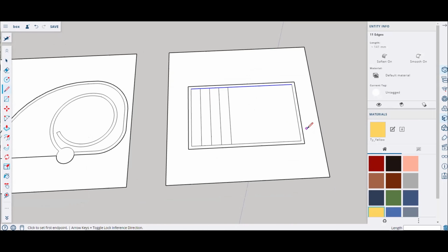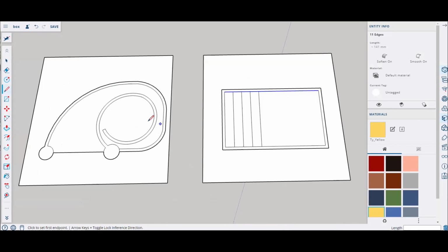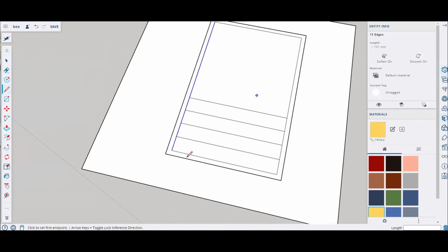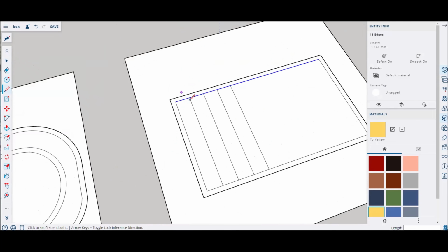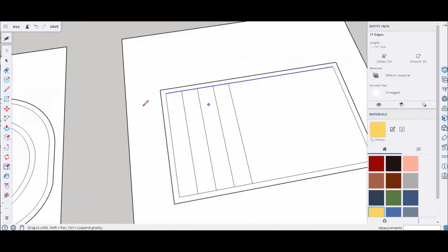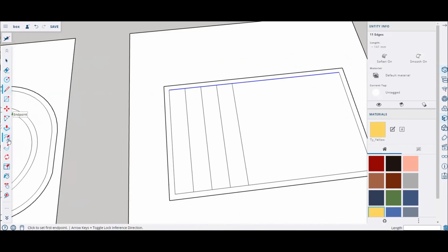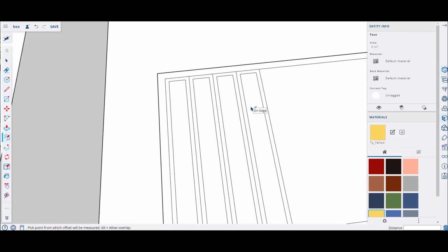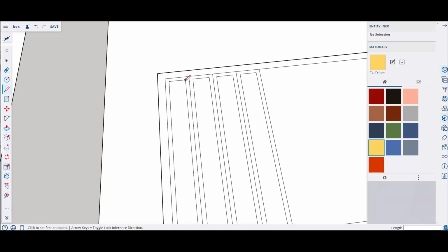And let's say that's where I wanted to be. You saw how I made the Fibonacci box. I'm going to use the same method now here. So if I put my mouse here, it's 13 mil, 13 mil perfectly. I'll use the offset button and I'll come in 2 mil on one side, 2 on the other. So that way I've got a thickness of 4 mil all around.